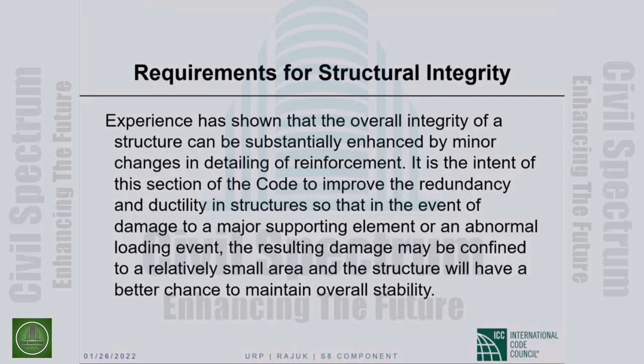The spacing of the transverse reinforcement is where requirements are relaxed from what they are for the columns of the superstructure. If you are talking Dhaka, it is design category C or D. In newer parts of Dhaka, it is design category D. So you will have special moment frame columns in your superstructure, and the transverse reinforcement requirements for the piles will be more relaxed.